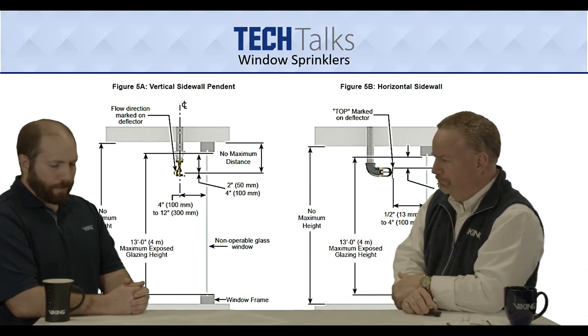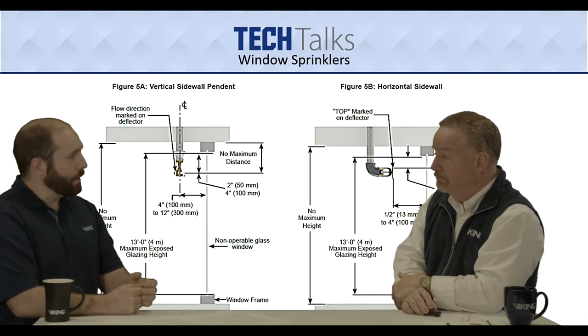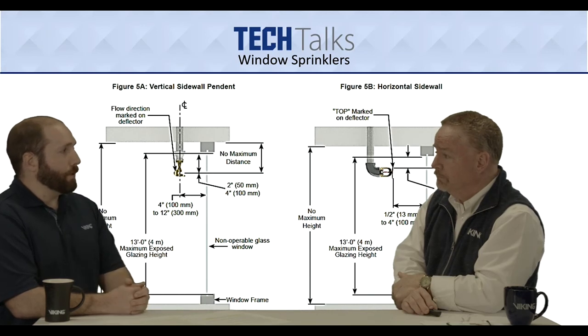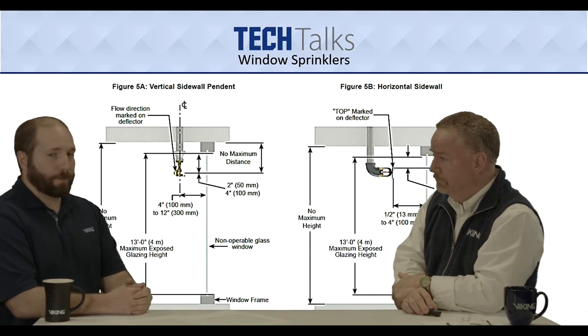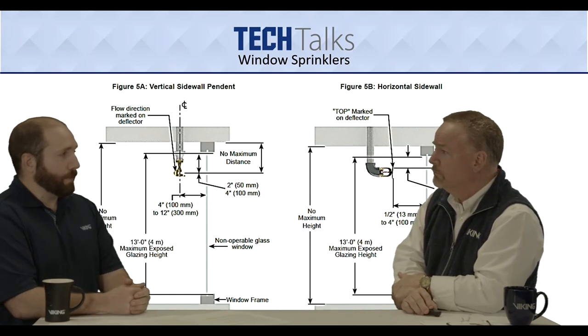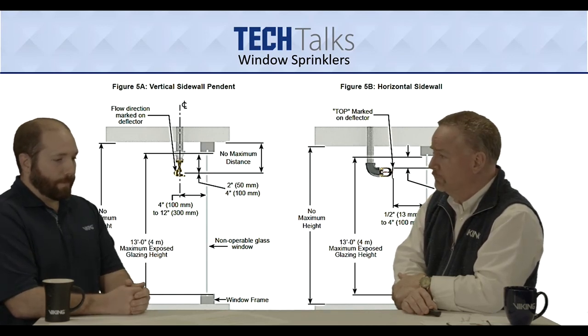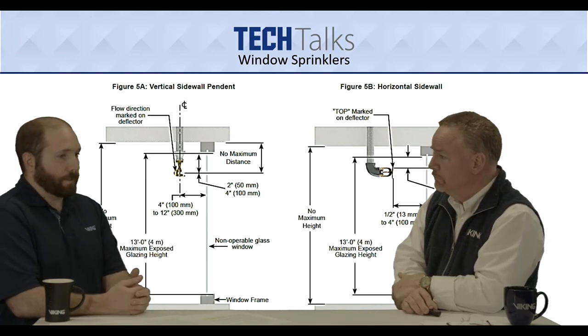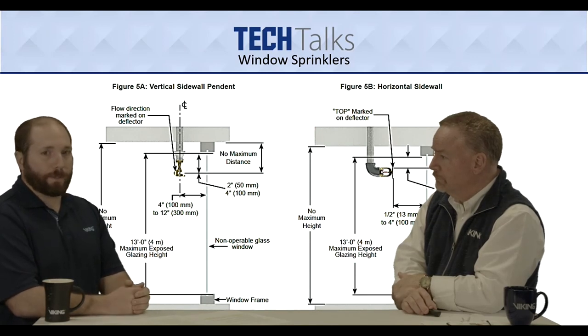There was one other question that I typically get. Could it be used as an open sprinkler? Absolutely. It can be used in a deluge application, open, or it could be closed, an automatic type sprinkler where it's got the element installed. So either way is an option, and that's laid out on page 4 of our data sheet in the UL design criteria.